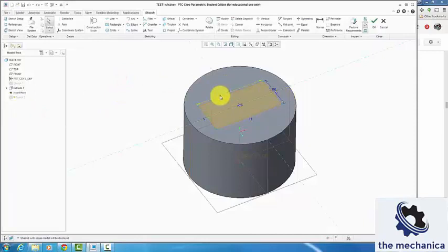If I want it to be square, and I know that from now on I just want this to be square, I click on that dimension, hit delete, and now it went back to a weak dimension, not a strong dimension. I can have my constraints up here, so I can put in geometric constraints to control things, so I don't need to use numerical dimensions, and that's a preferred way of doing things. So if I know I want this to be square, I can go to Equal, click that line, and click that line. Escape to get out of the equal.